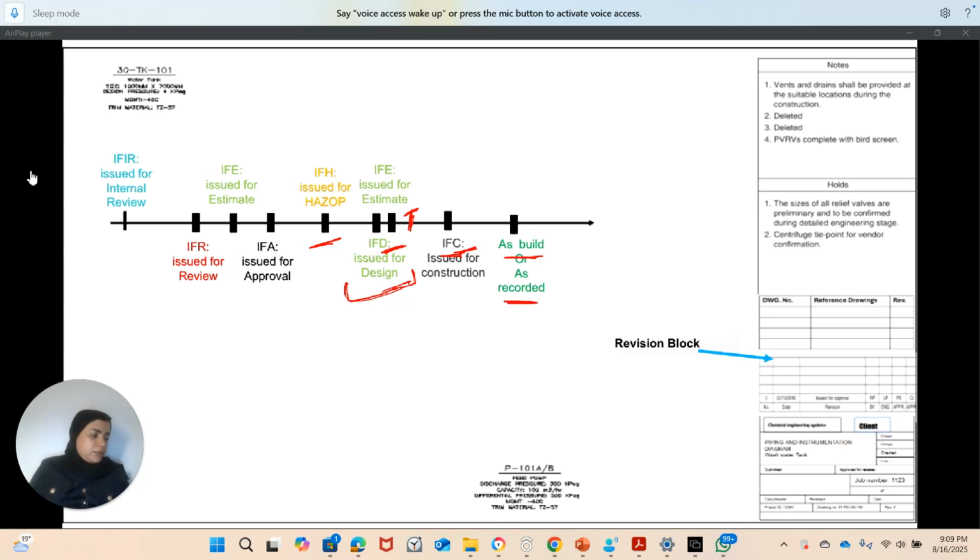And in some cases, for legality, they don't say as-built, they say as-recorded, because the difference is that as-built is when you physically send an engineer to do line tracing. In this case, the engineer will follow all of the lines in the refinery or the chemical plant, and he will come up with comments in the P&ID.